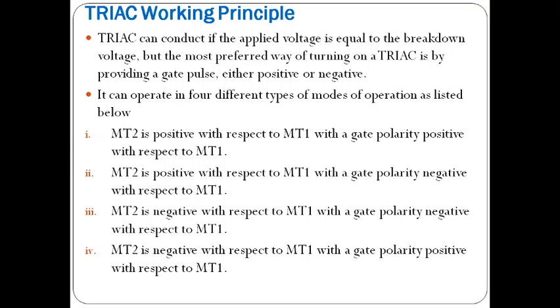Like SCR, here also this triac can conduct if the voltage equals the breakdown voltage, or by supplying the gate pulse to the triac circuit. So here the gate pulse may be a positive or negative.